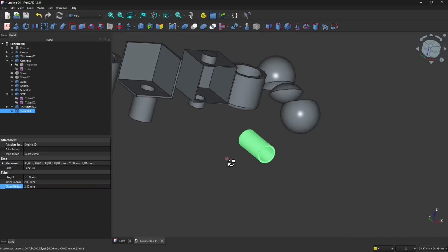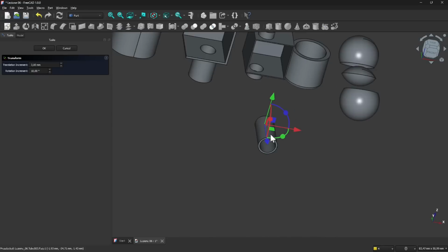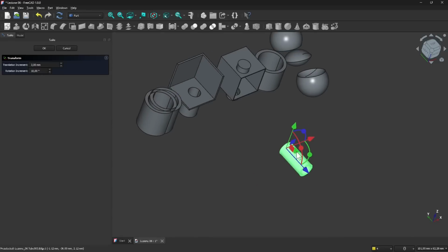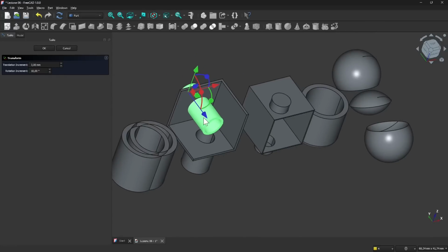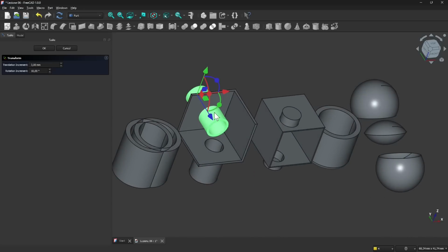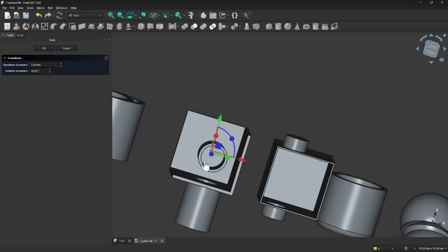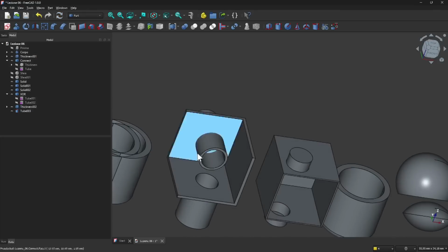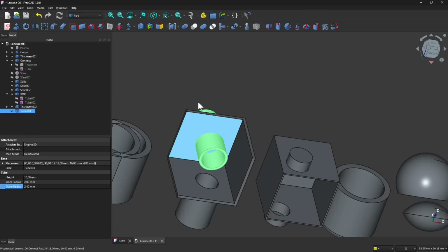Okay, and now I'm going to put this using again the transform. I want to put this into this other shape right here, that I already used, but you can create another one using again the thickness, or you can use another tube if you want. So let's say I want to add this to this, right? So if I do the simple Boolean, it's going to leave that part. Let me show you here. Let's say okay. So if I use these two objects and unite with the standard union,